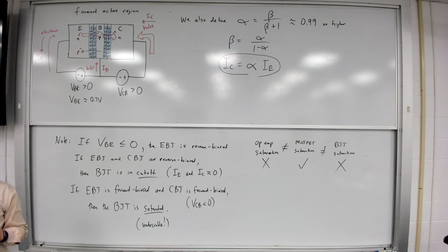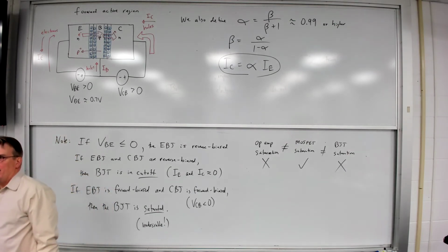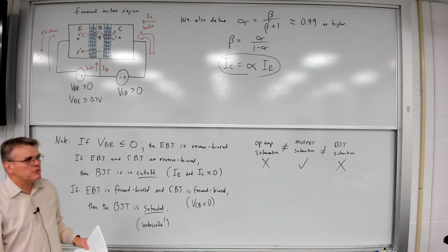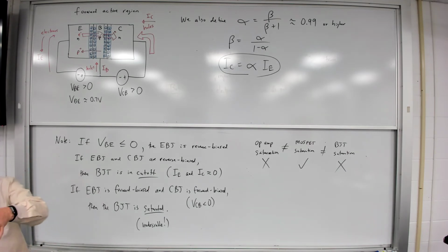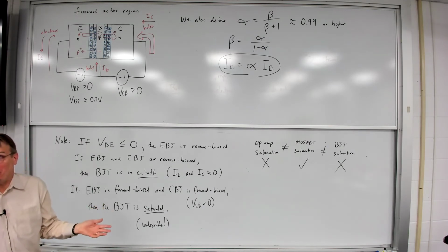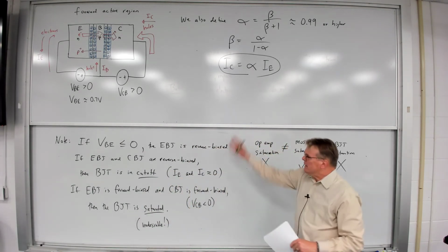And so, as we're going to see in just a minute, there is also a fourth region of operation, a reverse active region, which doesn't work very well and is almost never used, but it does exist. Basically, about the only way you can have reverse active is if you put the transistor in the circuit backwards. Then you'll know very quickly you did something wrong because the circuit simply won't work. All right? So just to add a couple other things to this.